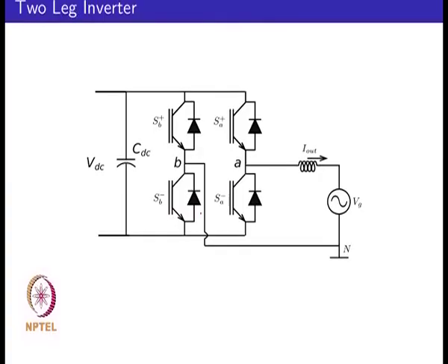So, one thing that also to keep in mind is that we were looking at the operation of this power converter from the input and output voltage waveform basis. Another important factor to keep in mind is how these legs of the power converter would operate on a thermal basis. If you are switching, say, one leg at FSW at the carrier frequency and the other leg at fundamental frequency, it means that one leg is having higher losses and the other leg is having lower losses.